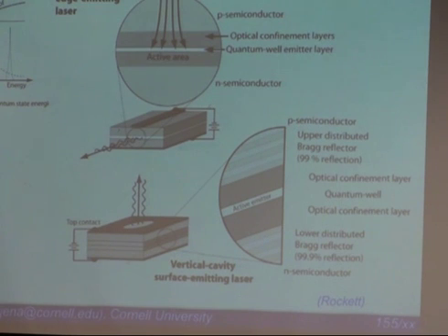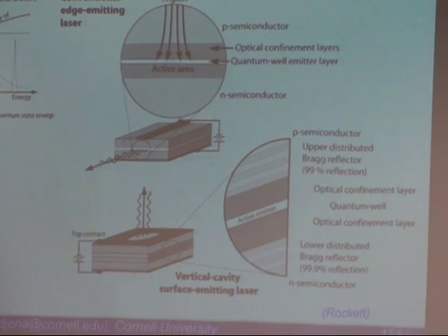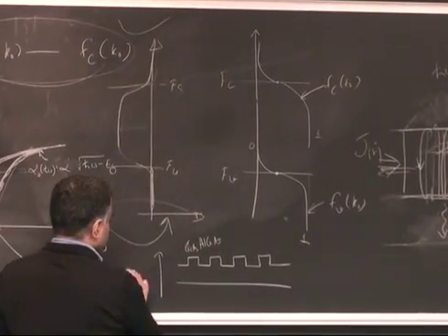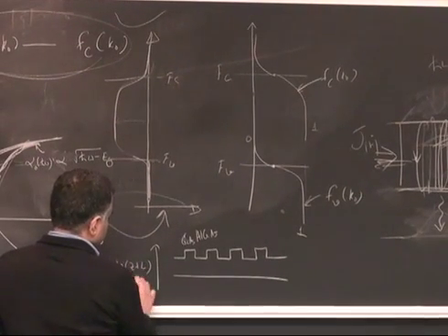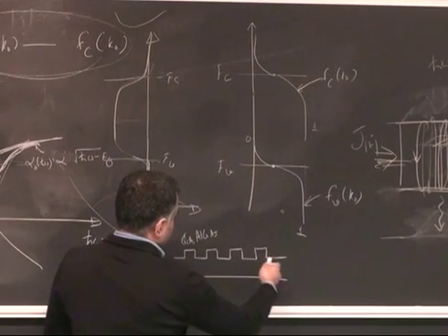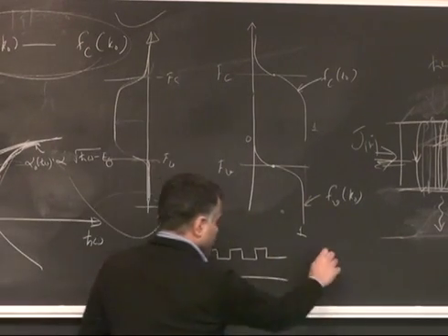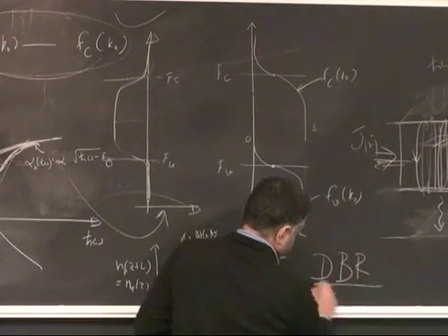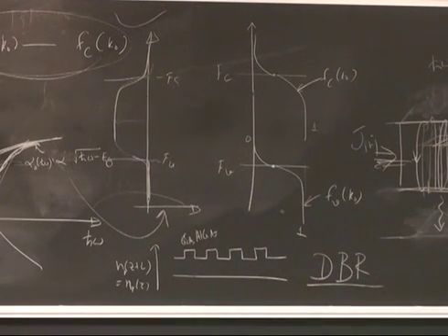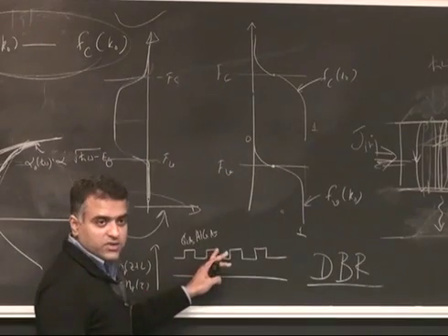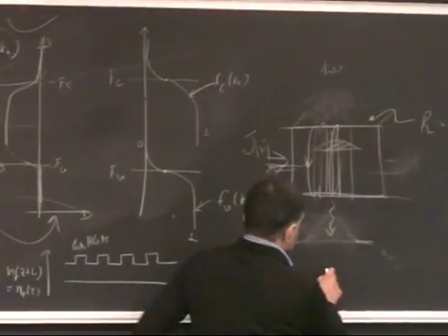So essentially, as you change the refractive index in this direction, even with a small value, you just kind of grow. These are typically called a superlattice of AlGaAs, for example. AlGaAs, larger band gap, smaller refractive index; GaAs, smaller band gap, larger refractive index. So basically, if your n(z) plus L, the refractive index becomes periodic, then you can actually do the numbers. You can calculate what would be the reflectivity of this sort of a distribution. So this would be called a DBR, or a distributed Bragg reflector. And typically with a few tens of periods, you can get reflectivity in a DBR close to 99.99%.